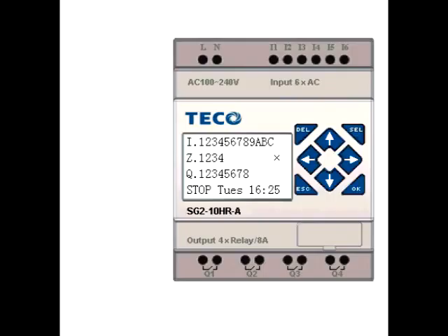This is a very important screen. This is what we call the I/O screen, and it's really the screen that allows you to go between the menu of operating the machine and the actual control. What you see at the top is your inputs, and input number 1 will be highlighted if you're calling for material, so you can use that for troubleshooting.